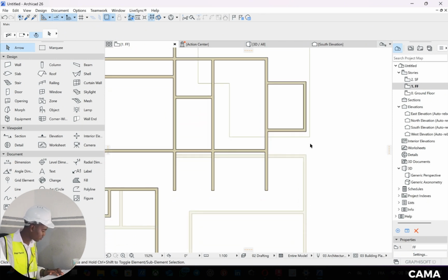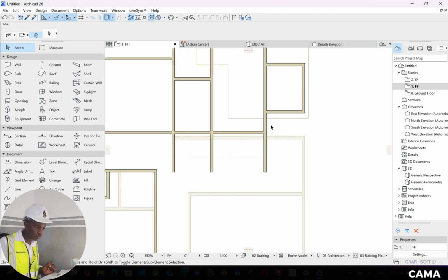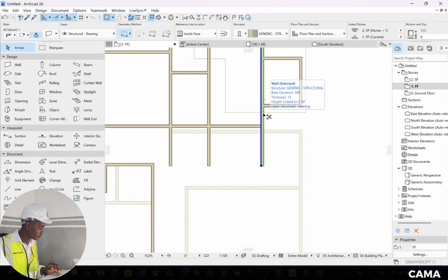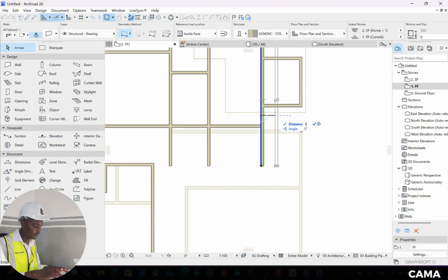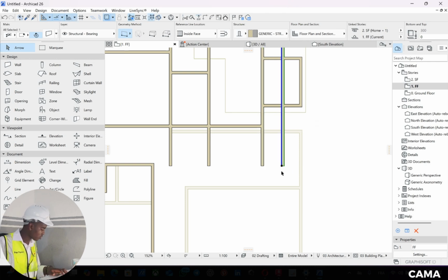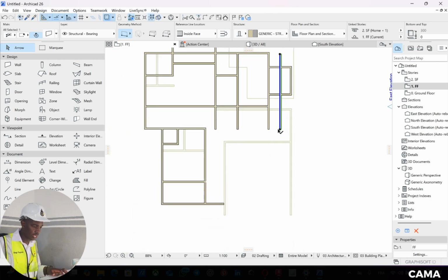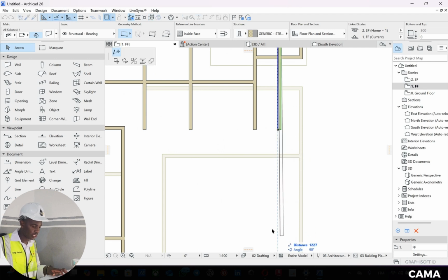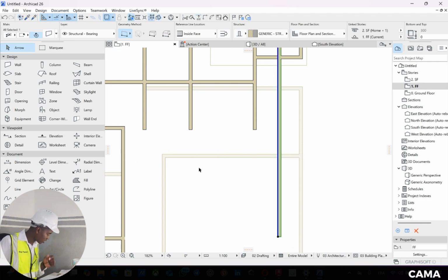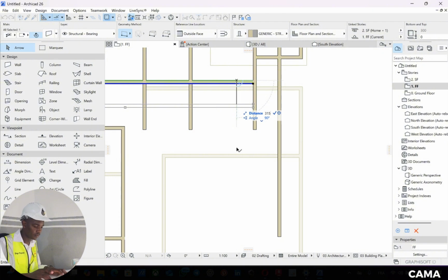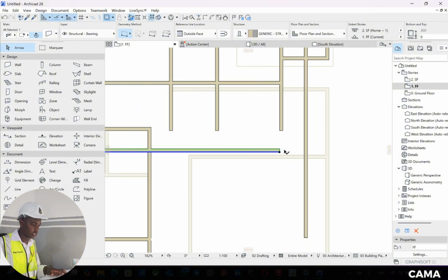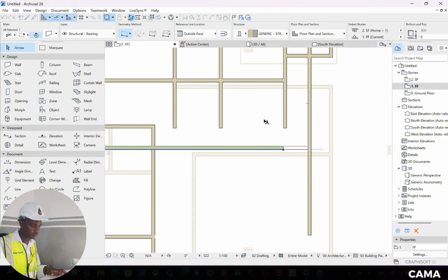Control, we delete, we delete, we delete these ones. They are not useful. Now you need to put the laundry room. We see that the laundry room from this line is 100 centimeters. That's 115. We press enter. We elongate the line like this. Then what's the size of our laundry room? 3 meters. That's Ctrl Shift D, 315. Enter. Then you extend it.